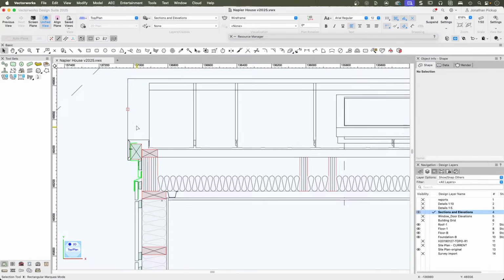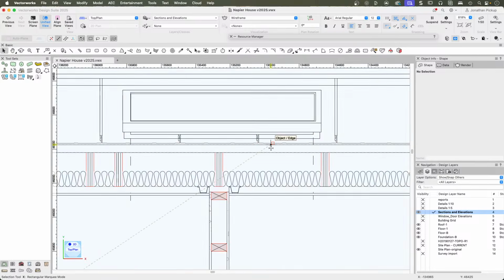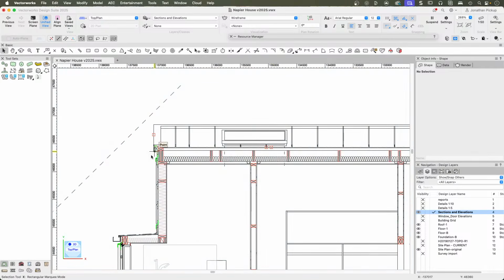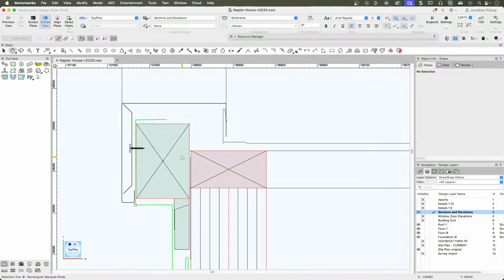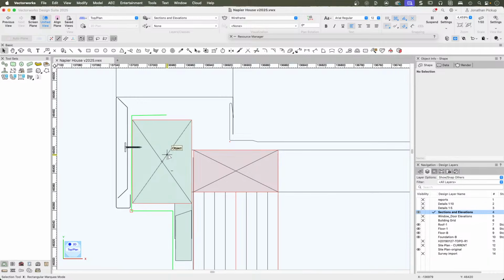There's my roof detail. I've taken some of these roof details and I'll draw them in this level of detail. Also notice that when I draw these, I draw them so that the objects are separated. Some parts I import from the manufacturer. This barge flashing here, I imported from the manufacturer. This is the way they want it to work. It's got a clip fixing system and they rivet it to the roofing here.